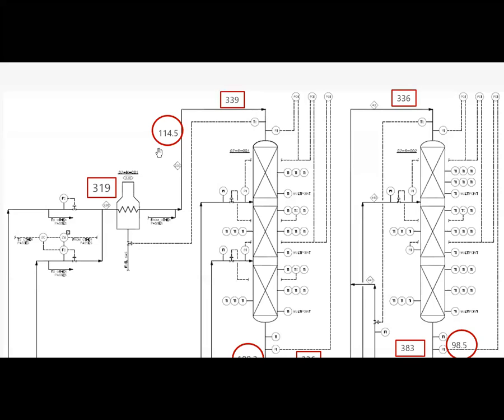Here you have the pressure. You see here that we operate at high pressure, at 114 kilograms per square centimeter. Then you have here the reactor 1. Remember that we said that we have 3 beds. You see it clearly, 3 beds. And you will have here a lot of temperature indicators across the bed, in the bed, at every point here.